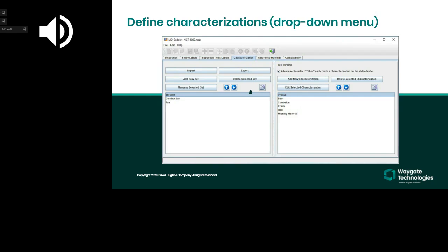Then when you're looking through the manual, it will tell you to inspect for, does everything look normal? Or do you see cracks or corrosion or missing material? What is it that you're experiencing? And now you have to document it. I've seen people spell burned with a T or an ED, and so now we're going to spell it the way the EMM, the engine maintenance manual, or whatever you're actually using for guiding your inspection, so that your report at the end of the day matches what the manual says to look for. Normal is best, but if you find something out, you can tag it with what you found.